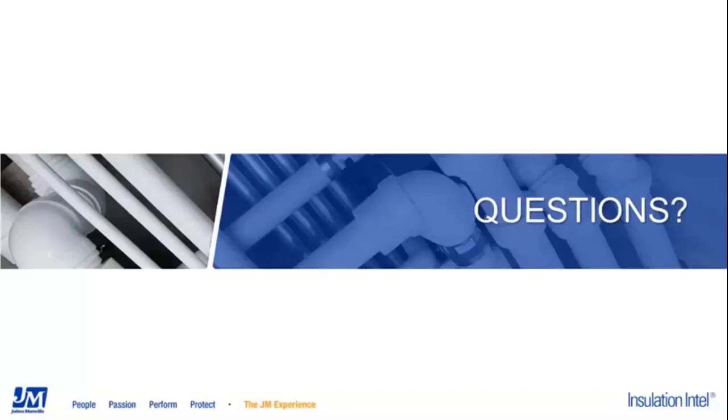The next question is, again for you, Meredith: does JM offer preformed and or prefabricated fiberglass fittings as opposed to field fabricating miters to match existing pipe insulation? If you're looking specifically for a fiberglass option for elbows, you could use our Zeston PVC covers, which come with fiberglass inserts. We don't actually make fabricated fiberglass elbows. You could also consider that we sell Trymer PIR to our fabricators that could then make fabricated PIR elbows, so that would be another option.